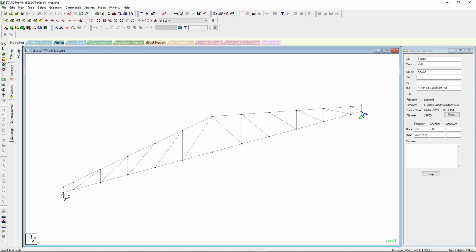Let's check. If you remember, I put the span as 15 meter, and you can find this STAAD model is made with the 15-meter span. This inclination I have fixed as 12 degrees, so this height is calculated accordingly. This should be 0.3, because in fabrication this top runner and this one have some gap between, so that's why I created this 0.3 gap.